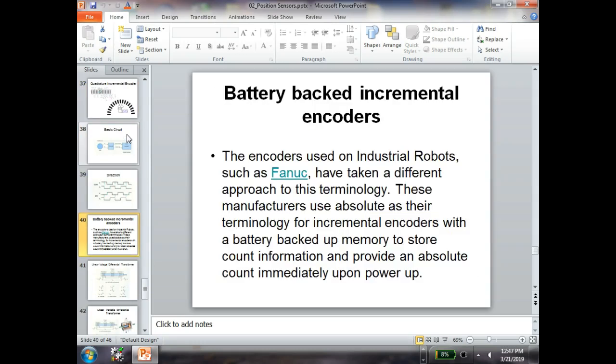Okay. You said the incremental encoder needs to know the position. Well, the incremental encoder doesn't know the position. That's the problem. All it does is send pulses. So what we have to do with an incremental encoder is establish what we call an origin. Where are we counting from? Once we've established an origin, basically they just clear out the counters and say, okay, this is 0. And then from then on, every pulse we get would mean a certain motion, depending on the transfer function between the encoder and what's actually moving, right?